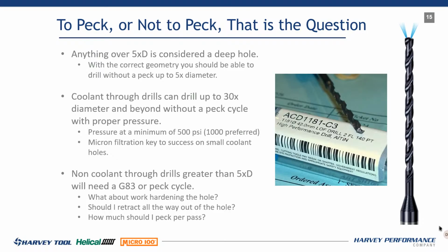Okay, what about work hardening the hole? I hear this all the time, and this is something I learned when I was younger, coming up through the ranks of making drills. You want to stay away from pecking because in certain materials, every time that drill hits the material as it evacuates, number one, you're putting damage on the end of the drill. And number two, you could be work hardening the top of that hole every time you go through, right? There might be some good drill guys out there who say, hey, listen, I want to stay engaged. I want to make a chip. I want to get through there. I don't want to keep pecking that drill.